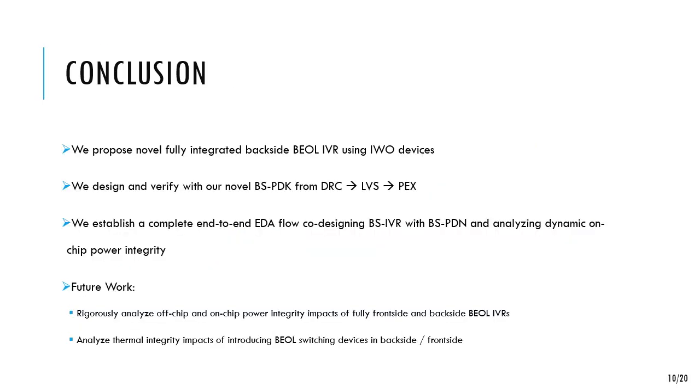Conclusion: our work can be broken down in three folds, where we introduce the first novel back-end-of-line fully backside integrated voltage regulator, leveraging back-end-of-line tungsten-doped indium oxide devices. We develop a novel backside PDK to rigorously physically design and analyze our voltage regulator and evaluate it as appropriately as possible based on commercial technology nodes. And we have a supported flow from DRC to LVS to parasitic extraction.